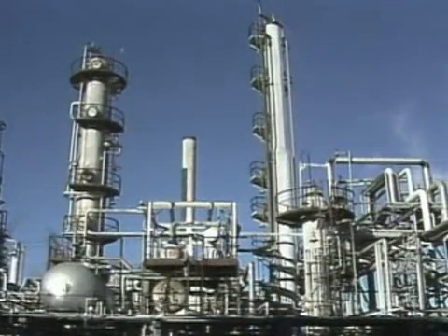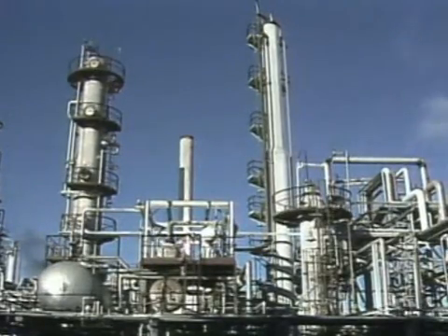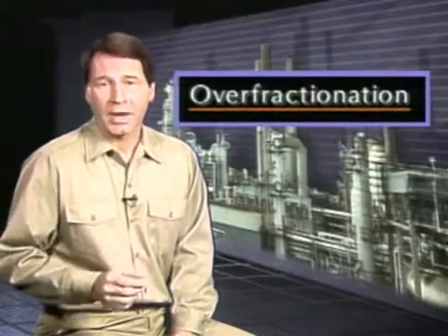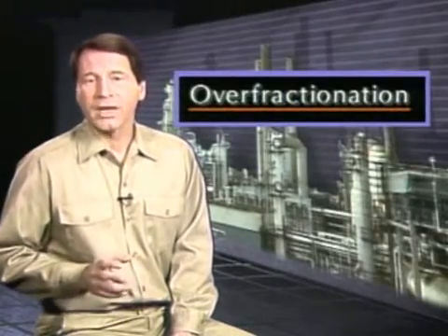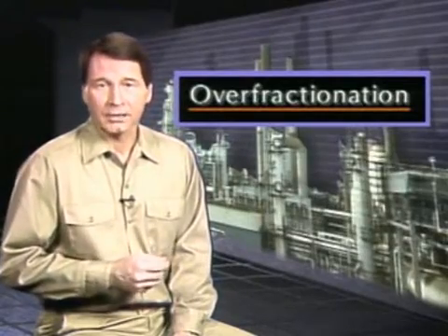Distillation systems use a lot of energy. The key to maximizing efficiency is to produce on-spec products with the least amount of energy consumption. One problem that can interfere with efficient operation is over-fractionation. Over-fractionation results in the excessive use of steam and other utilities to produce products. Simply put, it involves using more heating and cooling than necessary.